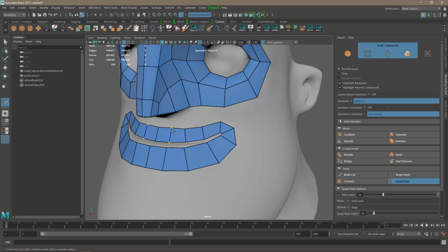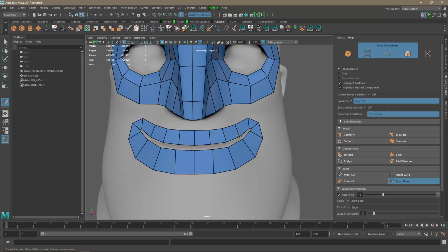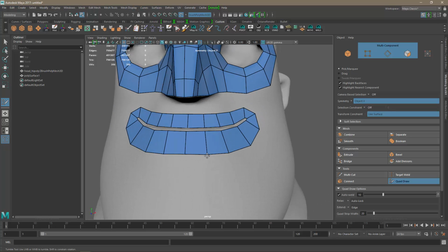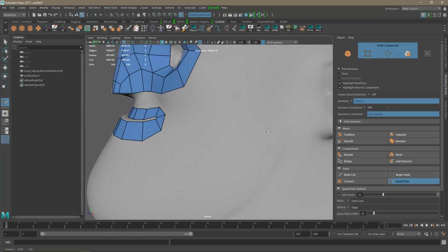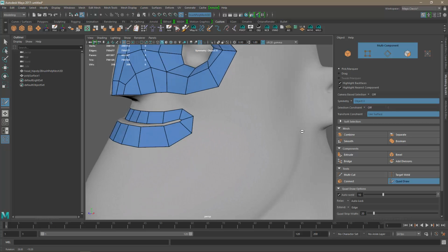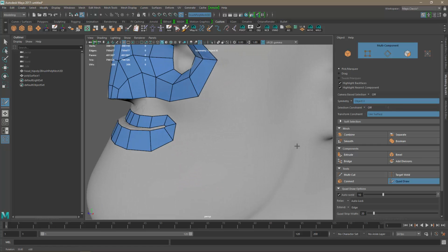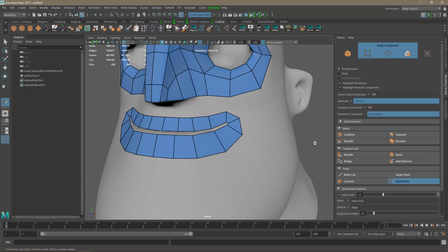all quads, because as I mentioned in a previous video, when you work with subdivision you do want to have quads, because triangles will generate some pinch, some pulls in the smoothness of the geometry, which is fine if you are over a flat surface. That doesn't really matter, but since this character it's all curvy, then you don't want to have that situation.